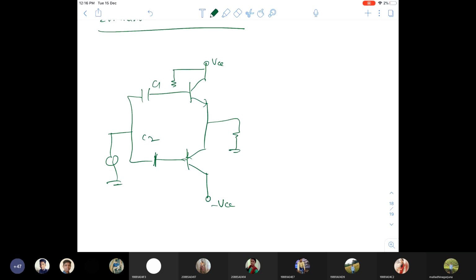I am connecting one resistor, and here I am connecting two diodes in series. Okay. What is the cut-in voltage of this? 0.7. This is 0.7, total also the total 1.4 volts. If you connect these diodes externally, what happens is the potential of the diodes will become 1.4. That 1.4 volts will be used to turn on the transistor without depending on the input signal.